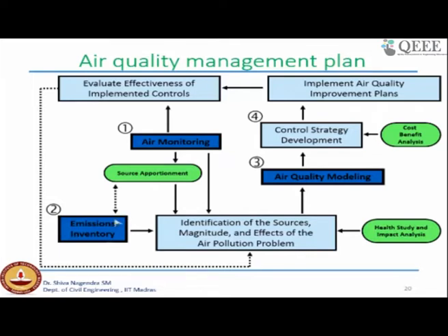In terms of numbers, two-wheelers are more, but they are not contributing a significant amount of emissions because they are all gasoline powered, and their emissions will be less. But heavy vehicles have very high emission factors, even though their percentage is very small, so their contribution will be much higher. So your emission inventory will be able to identify which source is contributing emissions in that particular area.